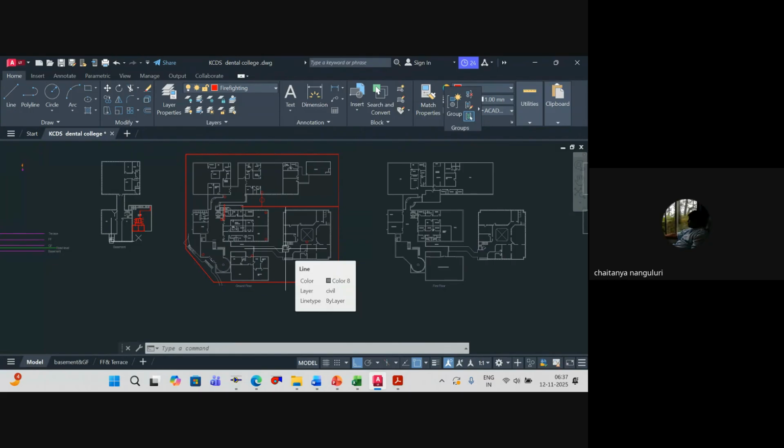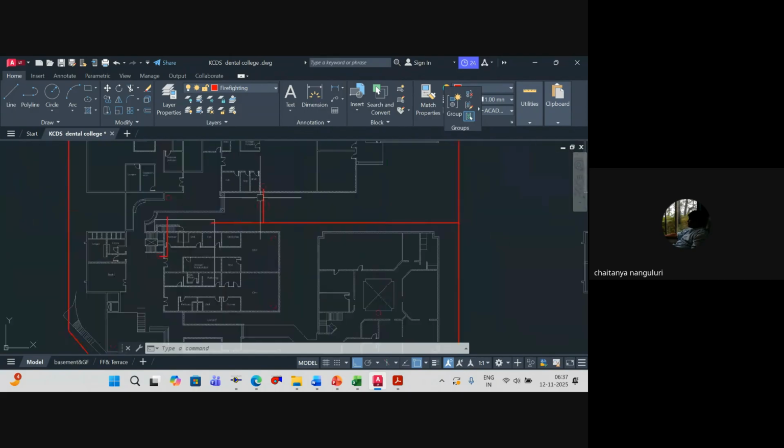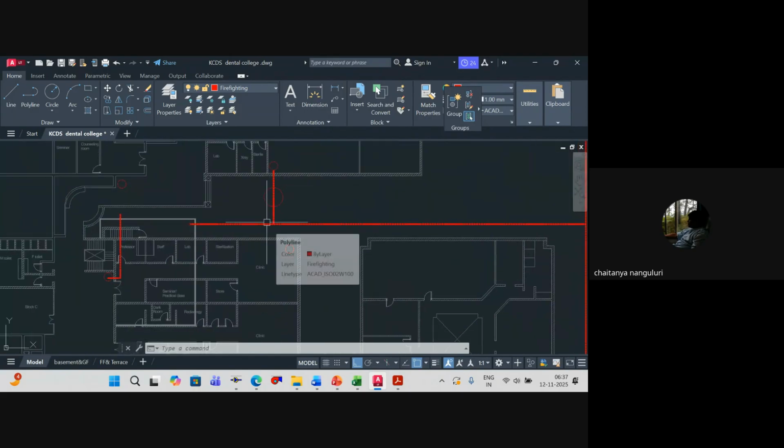So with that, we have to provide your alarm valve external to the building. Like that, we have to always provide it for any building. When you provide an alarm valve external to the building, you need not provide it in the pump room. Else, you have to take one particular pipe for hydrant and one particular pipe for sprinklers, and then you provide an isolation valve inside your pump room only.